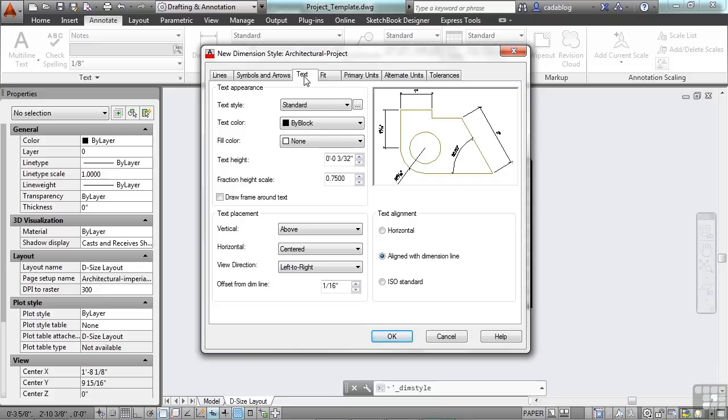Now, you can also find out that, hey, I need to tweak this drawing just a little bit, and that's okay to do. I suggest if you want to tweak a customized style, then you copy it, give it a name, and say, hey, it's based on this default style, but it's just a little bit different. Maybe it's normal-bold or normal-italicized or something else. That will help you know that you've tweaked it, it's special, and that it's okay to copy and paste it around. It's not going to override any other type of dimension styles at all.